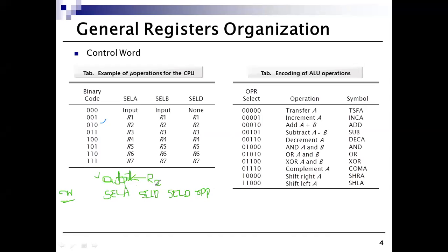The first input is any of the 7 registers, that is R2 we are using for select line A. Everywhere we have transfer operations with A bus, you have to use mux A only. So SELA is 0, 1, 0.